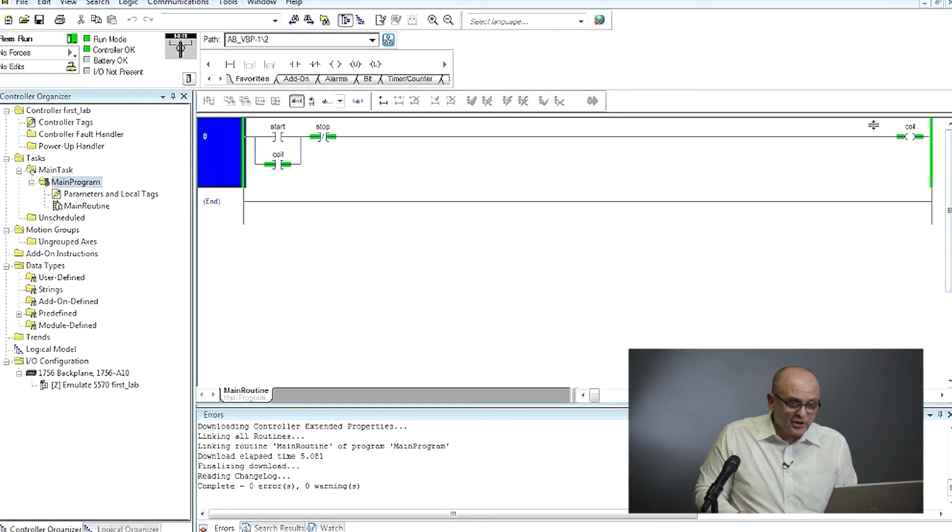One important rule is that you never ever duplicate outputs. The output can only be used once. Inputs don't matter. Again, this instruction is auto latch, used for the main power of the machine, and the auto latch contact is an input instruction with an output address.